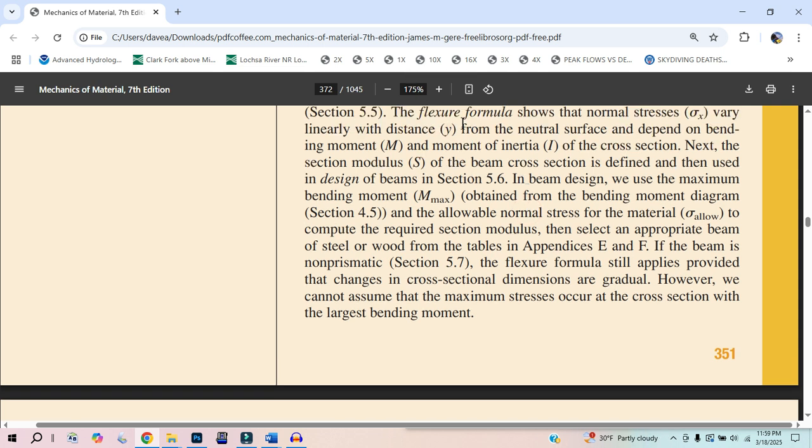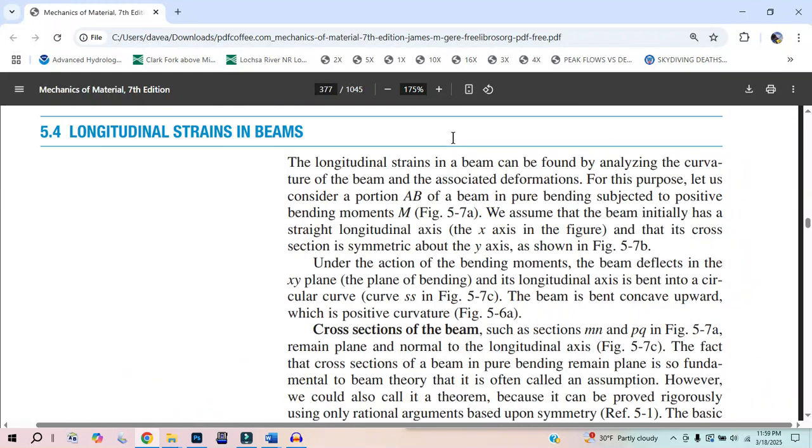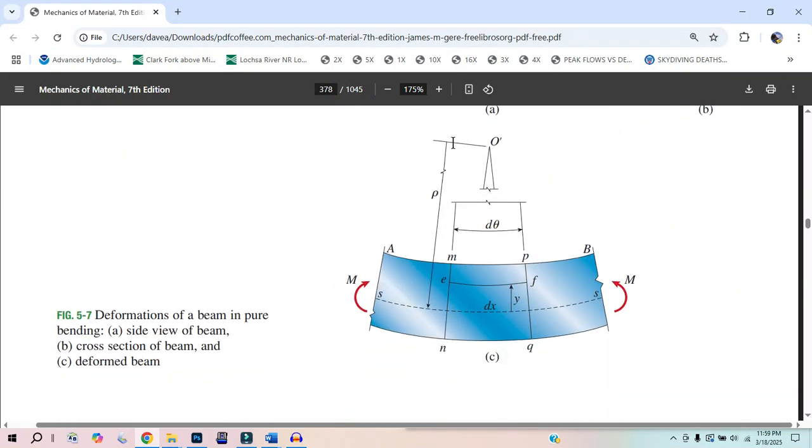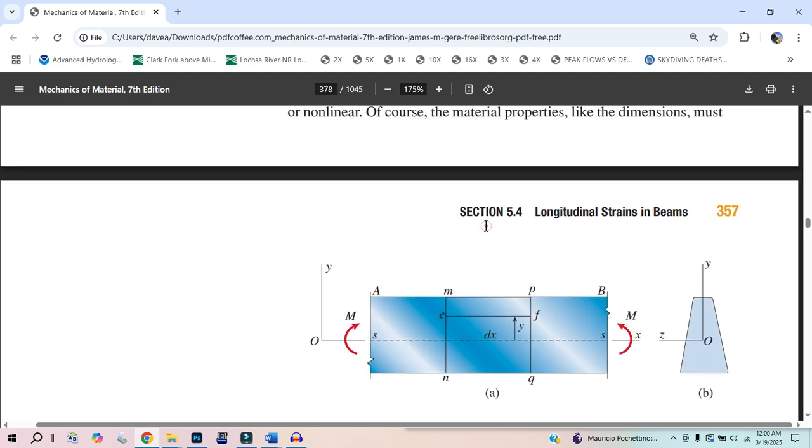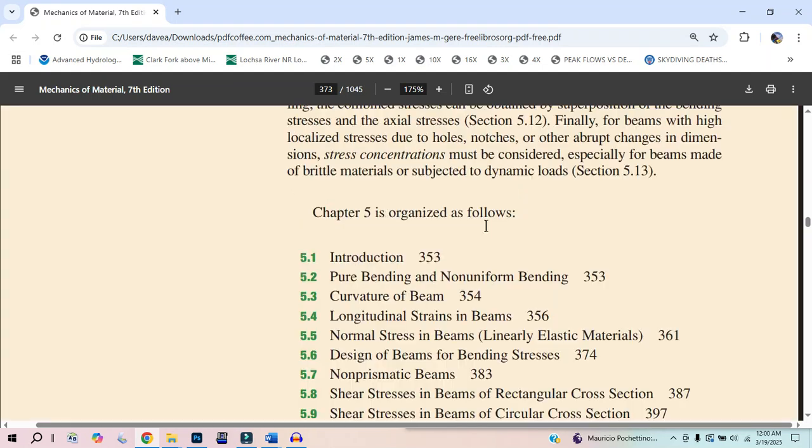Cool. And this y can sometimes be called y max, you know what I mean? And it's good in material mechanics to put different labels on things. So if this is y max, well, is it y max in compression, y max in tension? That's where you can be like, hey, for this problem, you're going to have two y max values. This one is going to be max compression, and it's going to have this distance. So that number is going to be a taller distance than this. And so maybe you would call this y max in compression. This would be y max in tension. All right, booyah.